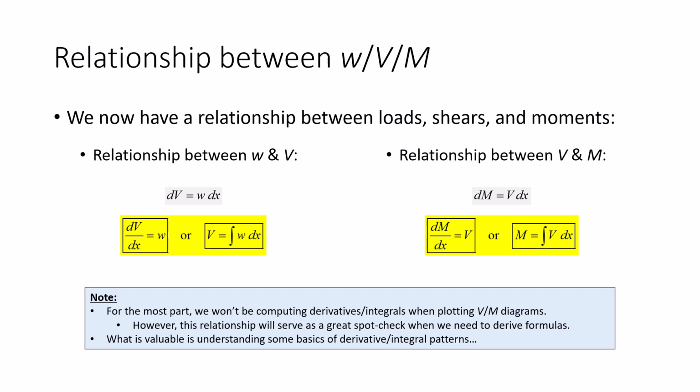Every now and then we have a triangular load, but for the vast majority of applications in real world engineering, we deal with simple loads. And because we have an inherent understanding of the derivative and integral relationship with polynomials, we can develop a graphical means of constructing shear moment diagrams and avoid the calculus altogether.